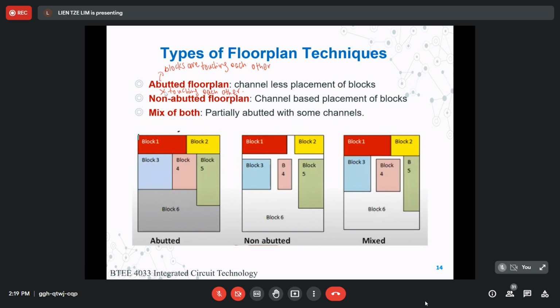For an abutted floor plan, it means channel-less placement of blocks. Non-abutted is channel-based placement of blocks. And mix of both means partially abutted with some channels. The channels here we can understand as this part.